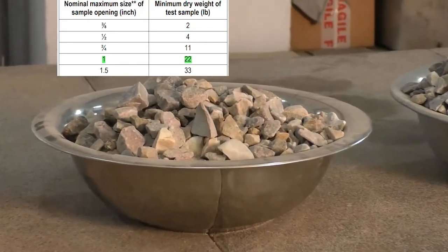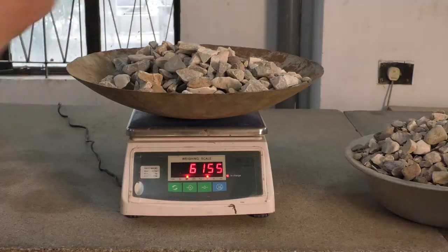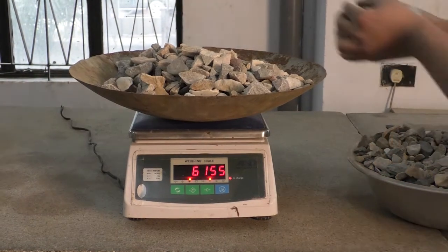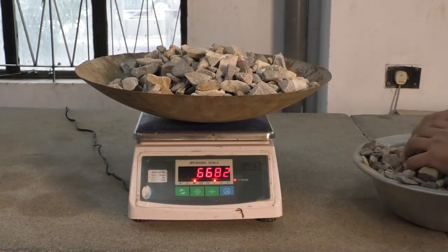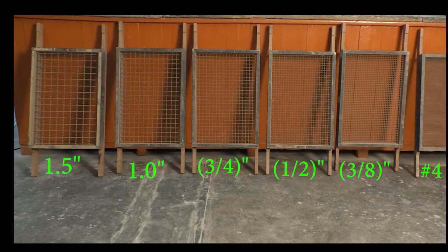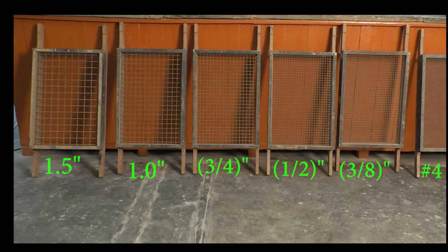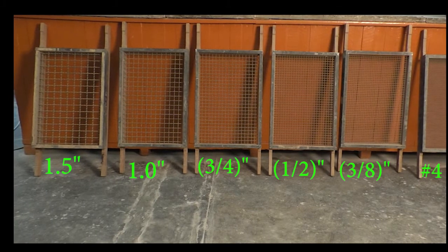A 1-inch downgrade coarse aggregate sample has been taken for the test. Therefore, we need to take a minimum of 22 pounds of the dry sample, which is equivalent to 10,000 grams. Here we can see the sieves taken for the sieve analysis of the coarse aggregate sample. Some non-standard sieves like the half-inch and the 1-inch sieve can also be seen here.